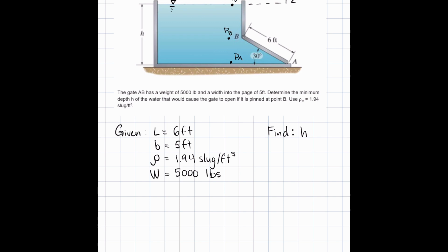All right, so now we're going to begin solving for these pressures. So PO at the top of the water, you can see that it's exposed to air, and we're going to go ahead and assume that that is just atmospheric pressure. And in order to make this problem a lot easier for us overall, we're going to assume that the whole problem is to be done in gauge pressures. You're going to get the same answer in the end, whether you use absolute or gauge pressures. So it's just going to simplify the math for us to assume that PATM is 0 kPa in gauge pressures.